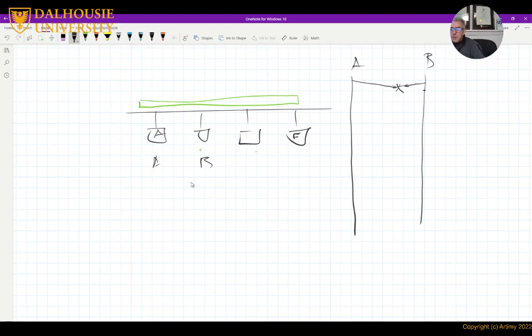So that happens. And that's why we need to, one, make the frame propagation time small compared to the frame time. And how do we make it small? By limiting the bus length. We limit the cable length. And I mentioned last lecture that we have a limitation of how far the cable goes. One of the reasons is so that we can control the TP.